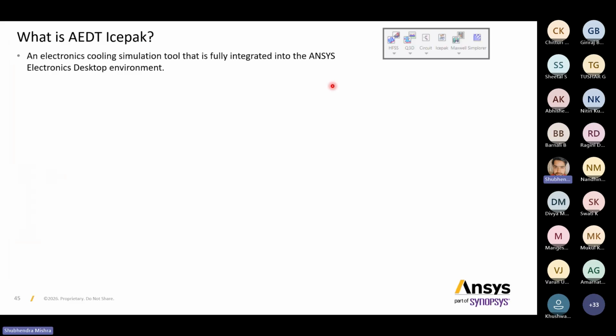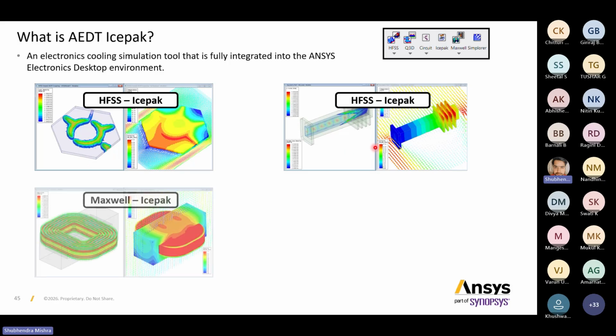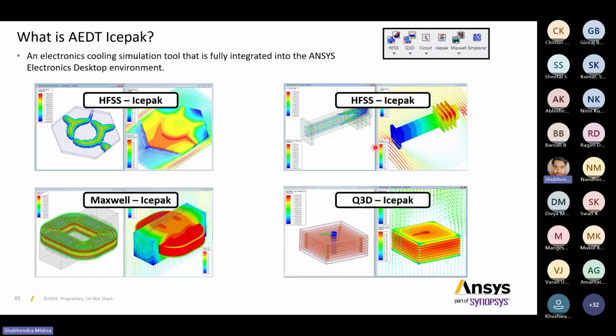When I talk about the ADT Icepak, this is basically a model where I can couple HFSS with Icepak for your simulation phases. Like where there is a waveguide, or a patch part, all these things we can evaluate from here. For power electronics also, like when I'm doing some coil analysis, I want to couple the Maxwell tool with Icepak. I can do that also. I can couple Q3D with Icepak. So Icepak is a tool which can be coupled with any of the environments.